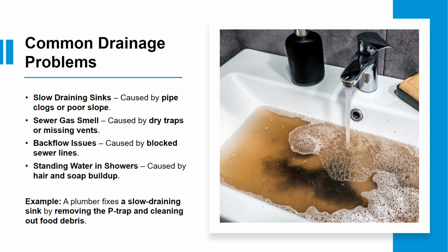5. Airlocks and gurgling. Lack of proper venting causes air to get trapped, affecting flow and causing noise. Solution? Ensure all traps are properly vented. These are real problems, and they happen when corners are cut. But you? You know better now.